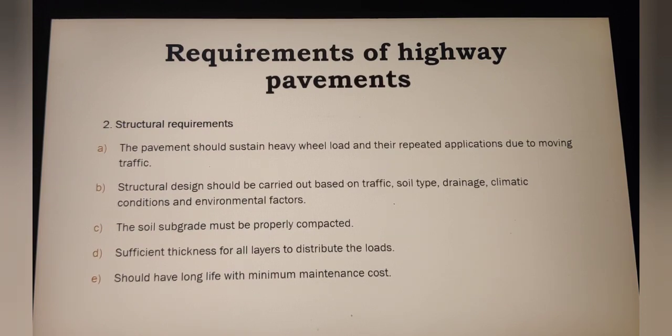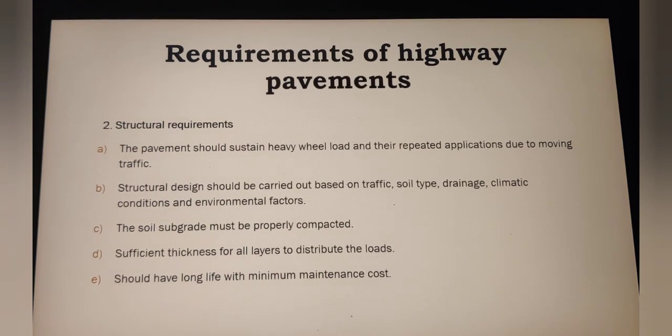So next is the structural requirements. Coming to the structural point of view, the first point is the pavement should withstand the heavy load and the repeated application due to the moving traffic. And the structural design is mainly carried out based on the traffic volume, type of soil, drainage, climatic condition and other environmental factors.